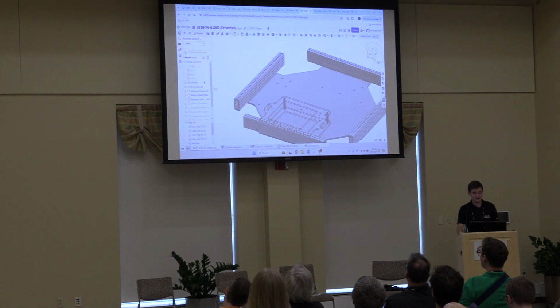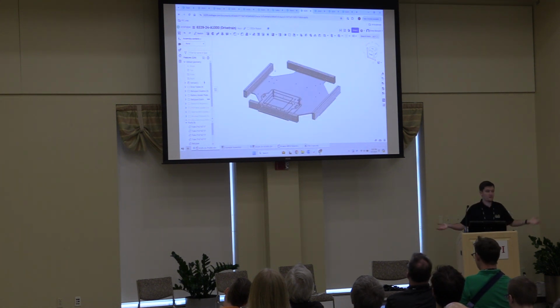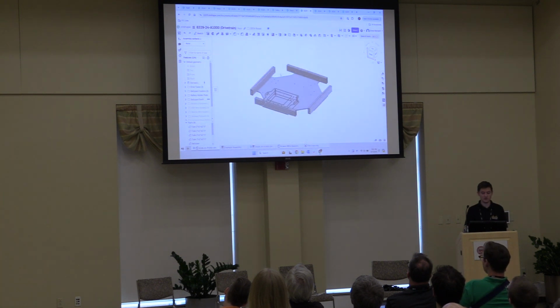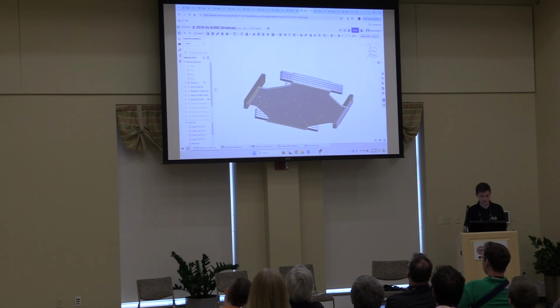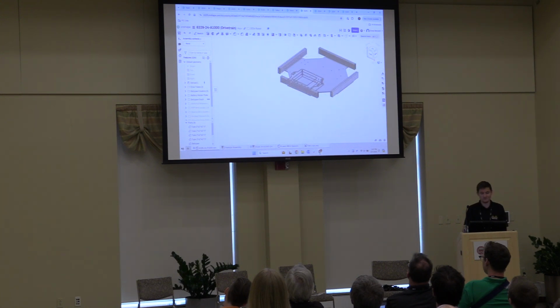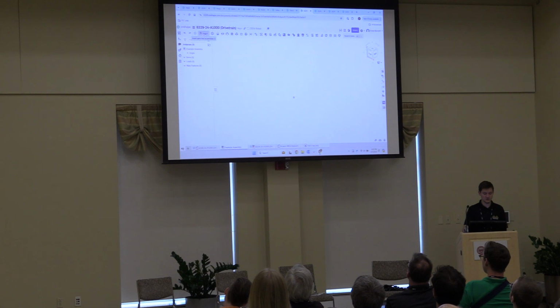Here's your example. This is the custom parts for a Mark IV swerve chassis. We've probably all modeled this before, and of course you could sit here and insert all the parts and fasten between the belly pan to this, to that, but it's a total waste of time. Because what you can do instead is insert, and I will just drop in all the parts at once.